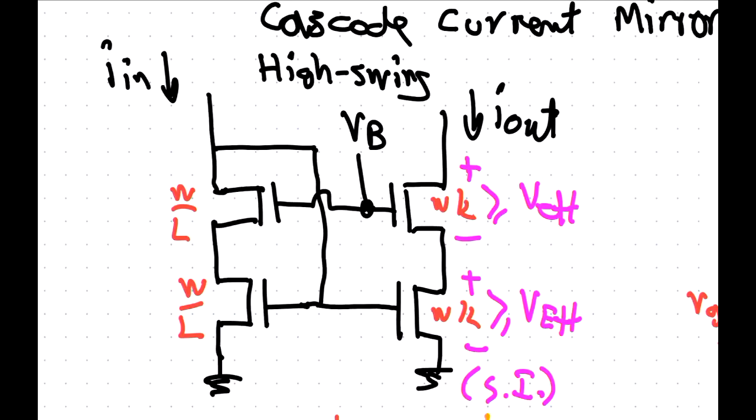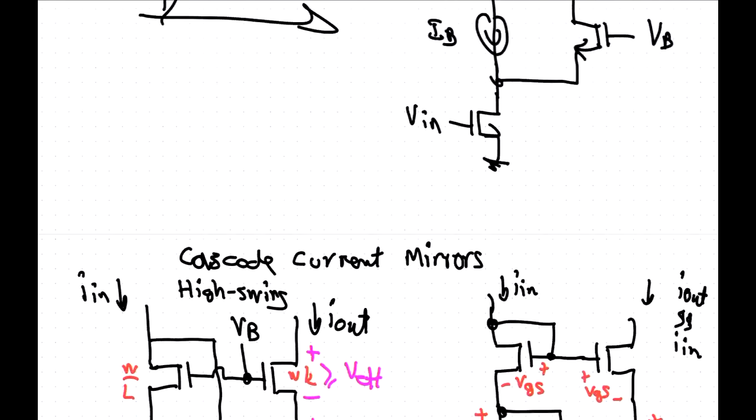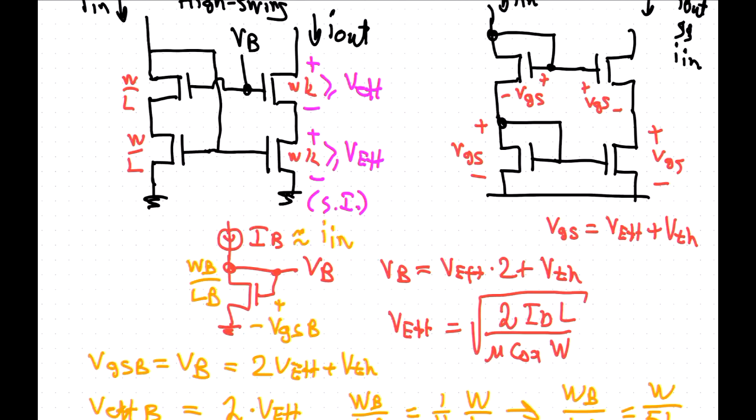And the last thing was, how do we bias the cascodes in the OTA? Do we just pick a voltage? Just like we did last time. This is how you bias a cascode. The common thing is to use a wide swing cascode, and you want to take process variation out of the equation as much as you can. You have some kind of bias current coming in. I'll talk later today about how to do that in more detail, but essentially you start with a current source.